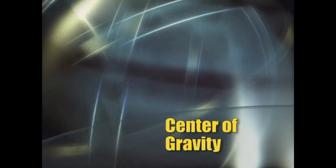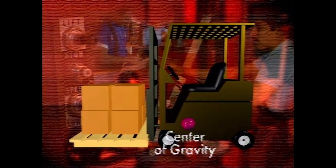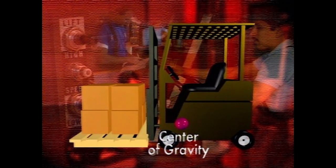Another engineering principle that affects your safe lifting capacity is the center of gravity. Technically, the center of gravity is the point on an object at which all the object's weight is concentrated. For symmetrical loads, the center of gravity is at the middle of the load. Certainly, if you have a forklift unloaded, you have one center of gravity. If you have a forklift with a load, that center of gravity changes. So the entire object, in this case the forklift and load, is the concentration of weight of the forklift and load.